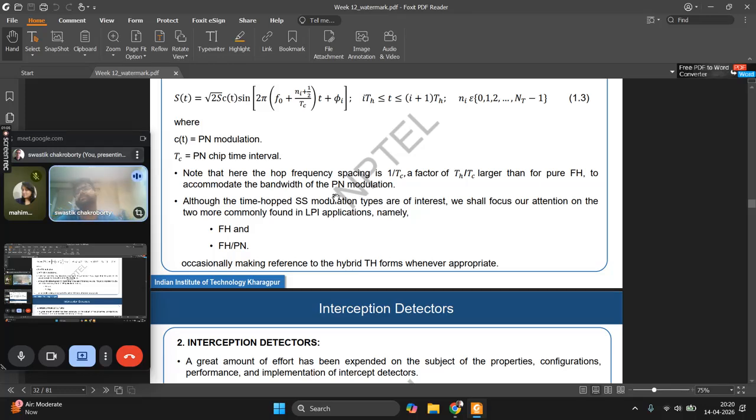So here we are sacrificing the advantage given by frequency hopping of managing in a smaller bandwidth, because conserving bandwidth is not our primary goal. The military usually has a reserved bandwidth which, for obvious reasons, only it uses. So conserving bandwidth is not a crucial factor for this application. Thus, we can safely give away the advantage that frequency hopping gives and get the 1 by Tc bandwidth instead of the 1 by Th bandwidth, which is much less.